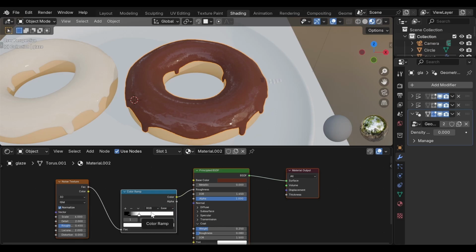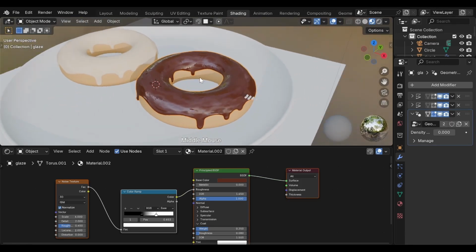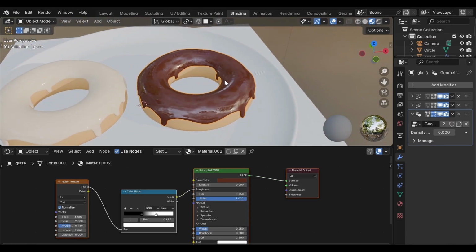It doesn't shift abruptly from glossy to rough. Move the black handle to around 0.35. This reduces how extreme the rough areas become. Move the white handle to about 0.65. This pulls the brighter reflections inward, making them smaller and more focused. With just these adjustments, the material already reads differently. Same structure, different light behavior.